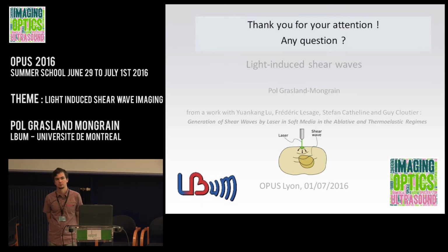Explorer? Yeah. Okay. And the displacement was only 0.02 micrometers, which is much less than a pixel of the camera, but still with correlation techniques. Yeah, in fact, it is quite lower than the spatial resolution of the ultrasound, but this is due to the fact that we track displacement, and even if we have a displacement which is lower than a pixel, we can find this displacement.